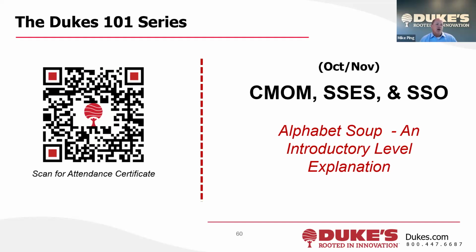I would say the most common would be at the wastewater treatment plant, at the headworks, the front end of the plant. Quite often they'll have what's called a drying bed where debris can be placed, and the water drains out into the treatment area. But the debris that comes out cannot be dumped on the ground. It's got a level classification, and it's got to go to a certified wastewater treatment facility or a place designated by the utility. The utility owns the debris.